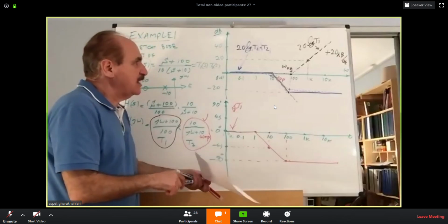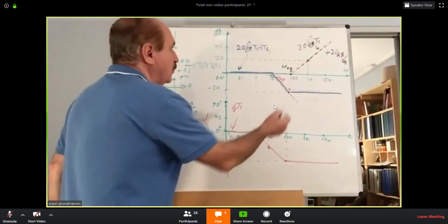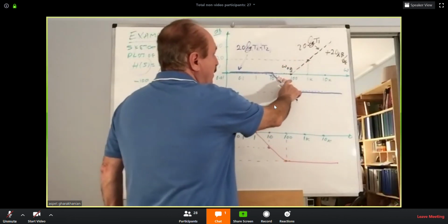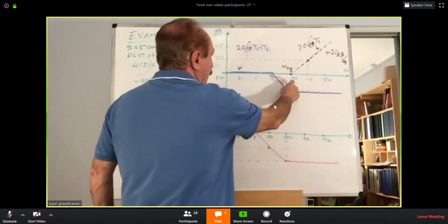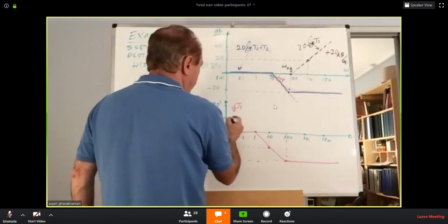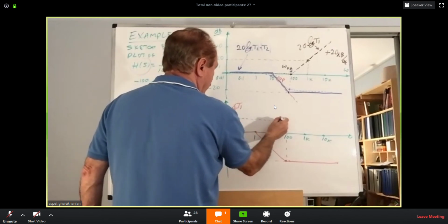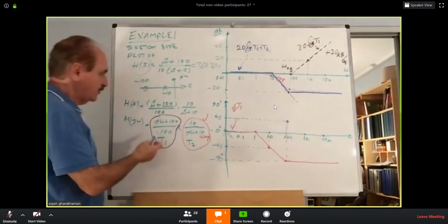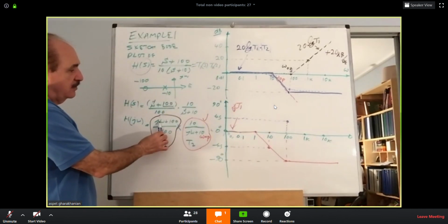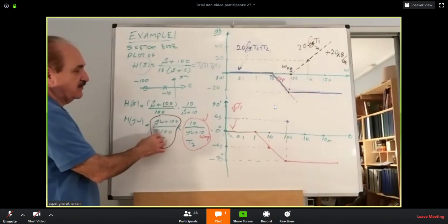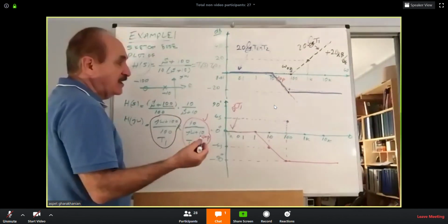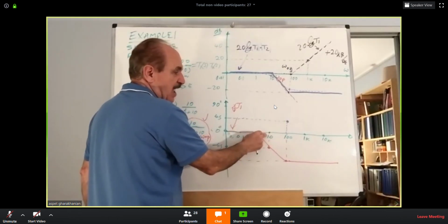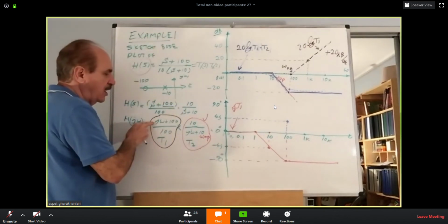Next, let's take a look at the angle of T2, which is the 0, this guy. This is the behavior. We know that at the break frequency, 100 here, they lead by 45 degrees. That's for the 0, because at omega equal to 100, the angle of the top is at 45 degrees. So you mark it. At a frequency much less than 100, say a tenth of the 100, which is 10, the angle of the top is almost like 0.